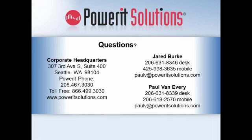Yeah, if I can add something else to that, Dick, that's a great question and something we've thought about quite a bit. One of the things that we've introduced into our SPARA technology is something we call an adaptive set point. We allow our customers to create a peak demand set point early in the month, and as their production requirements require them to set a higher peak above that set point they started with, our system naturally starts to adjust and increase the set point for them.